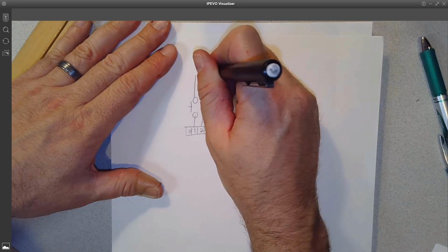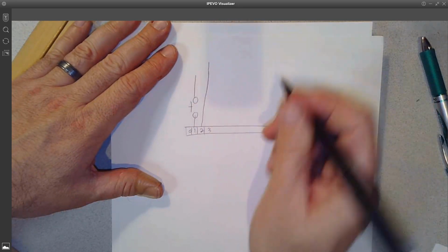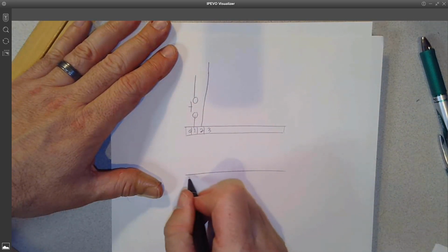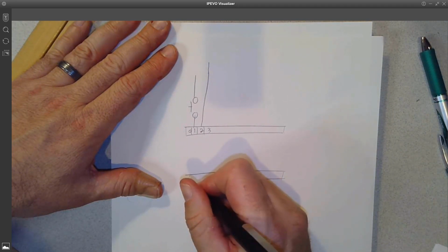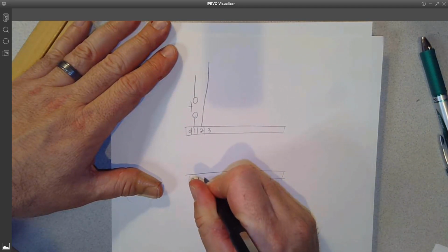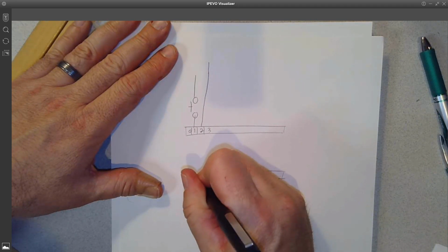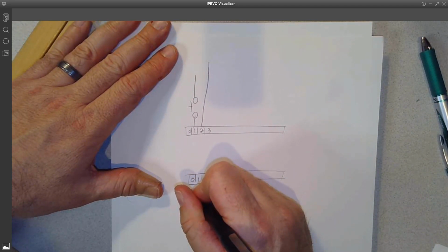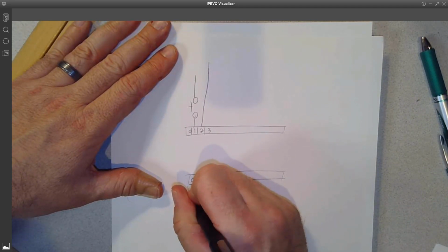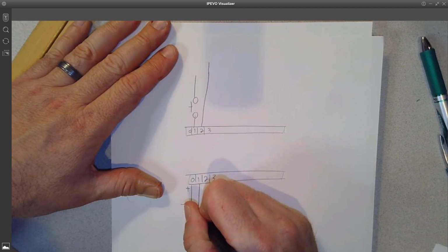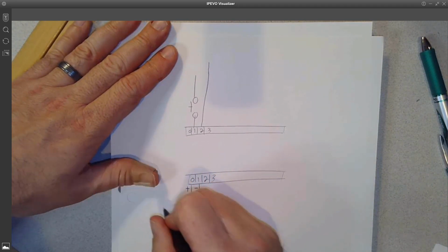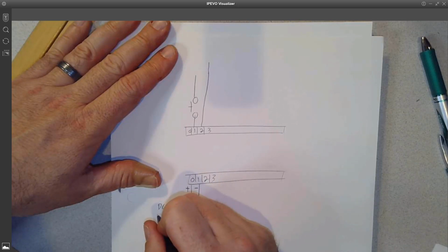And let's see, what else do we have? We could have the proximity switch on that one. Then down here, again, 1, 2, 3, on for all the terminals that you need. Say this one I think is power to the PLC. This one's negative, so you would label your DC power supply.